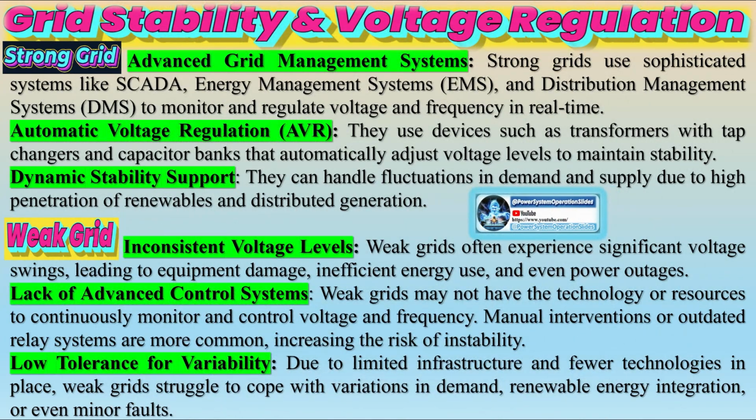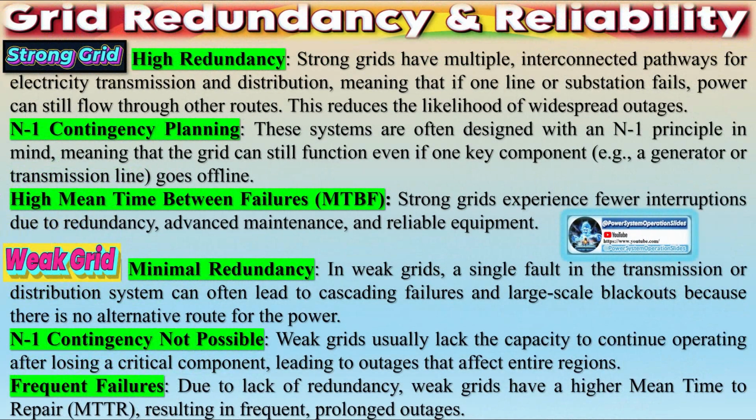Ground faults can be impacted by positive and negative sequence impedances but are often limited by the Thevenin zero sequence or ground impedance. Few spots on the grid have ground sources, such as delta-Y or zigzag transformer connections, on a solidly grounded grid. On high impedance or ungrounded systems, the grounding impedance, or lack thereof, completely limits ground fault current.